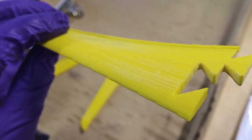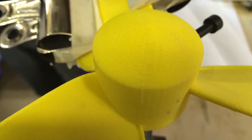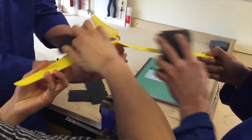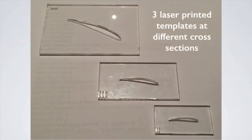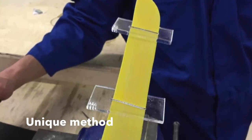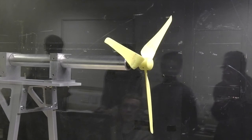The blades and the nose cone were manufactured using a 3D printer via a fused deposition method with ABS plastic. The 4 printed parts are then glued together. Extra material was sanded off the turbine to match the shape we desired. This process is assisted by 3 templates of laser-printed airfoil cross-sections at different locations along the blade. We consider these templates used for sanding another uniqueness for our group design, as it increased our manufacturing accuracy massively. The turbine is now ready to be tested.